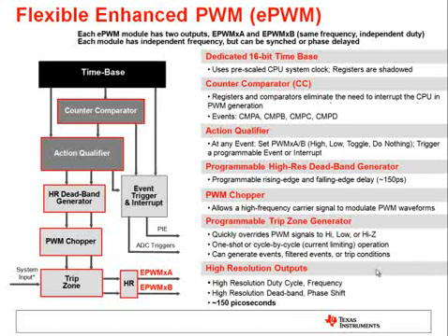The counter compare handles all of the compares to capture events, eliminating the need for extensive CPU interruption for PWM generation. It catches events and passes it on to the action qualifier. The action qualifier makes it even easier on the CPU because it can be programmed to automatically react to any event sent from the counter compare or interrupt and set the PWM output accordingly. This is essentially how the ePWM module works.